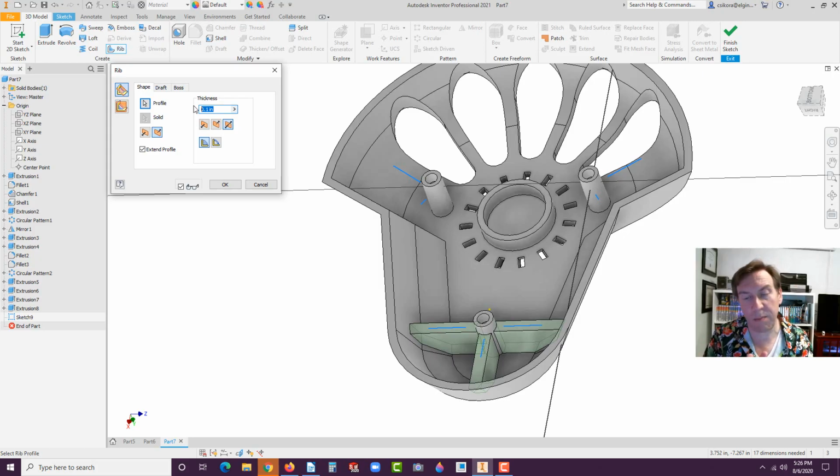And the reason why is because those masses of plastic, as they intersect, vertical ribs with the flat face, will actually cause sinkage when it cools. And it will sink, make little sink marks on the nice flat side. So it's not flat anymore. So if you've ever seen a poorly designed part, that's why someone didn't reduce this. So the overall wall thickness, if I'm correct, was 60 thousandths. I could look at the print and make sure, but I'm pretty sure it was.